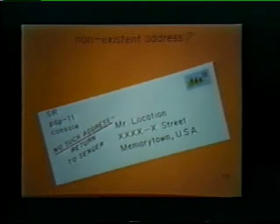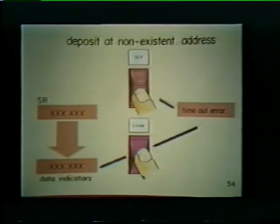What happens if we address a non-existent location when depositing information? Attempting to deposit in a non-existent location causes a timeout error. Although no visible error message results from this, an error indication can be displayed if the examine switch is subsequently pressed. Pressing examine causes the contents of the SR to be shown in the data indicators. Thus, the operator is informed of his unsuccessful attempt to access a location not included in the PDP-11 address space.